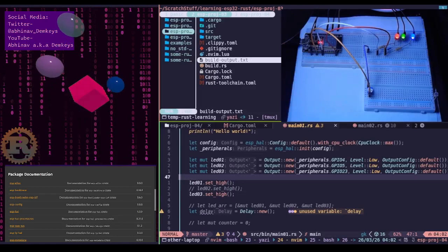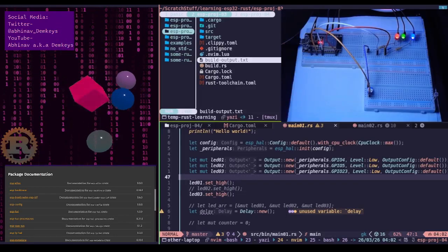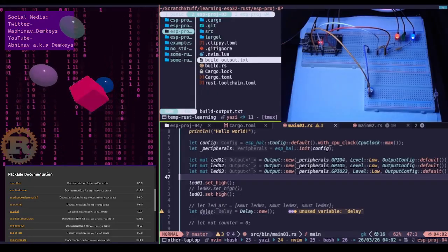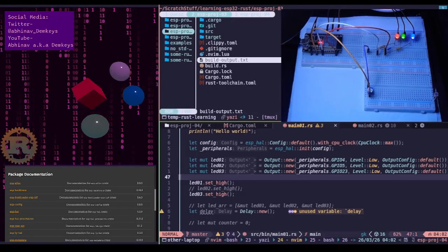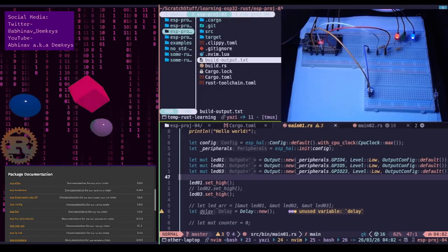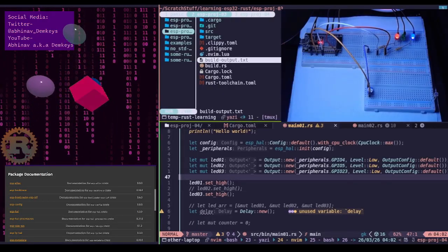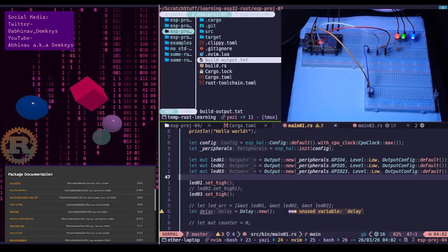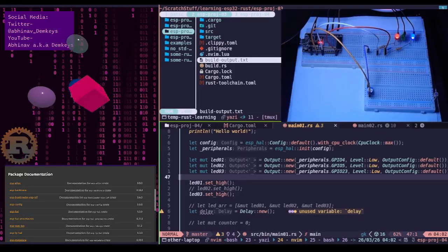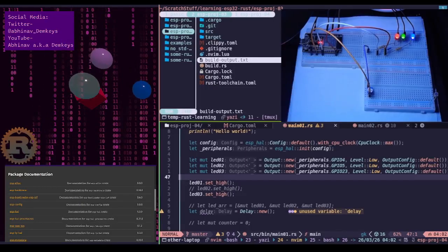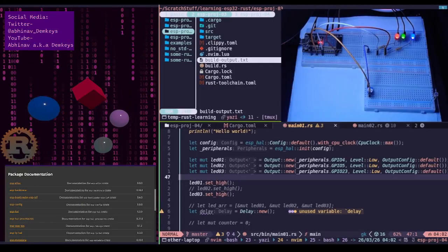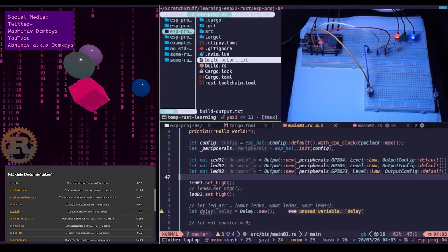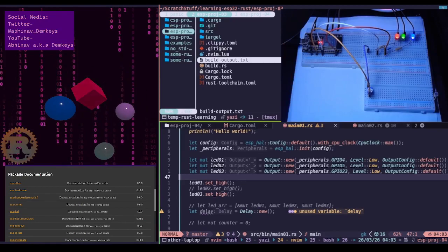Okay, the 3.3 volt golden rule. The ESP32 is not 5 volt tolerant on its GPIO pins. True, I do remember that. If you hook the potentiometer up to 5 volts, when you turn the knob all the way to the max, you'll be sending 5 volts directly into a pin rated for 3.3 volts. Okay, ensure pin 1 of your potentiometer is connected to the 3.3 volt pin on the ESP32.